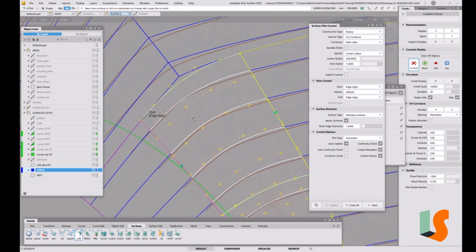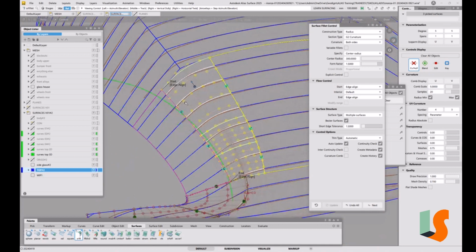It's saying as if we put in a fillet with only radius, then if you imagine a ball sitting between that surface and that surface, and you rolled it down between those 2 surfaces, that's where that ball would touch if the radius doesn't change. So that's what radius means there. It's slightly confusing, but that's what it does.